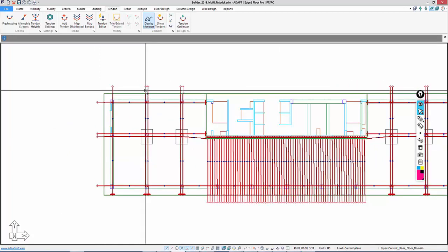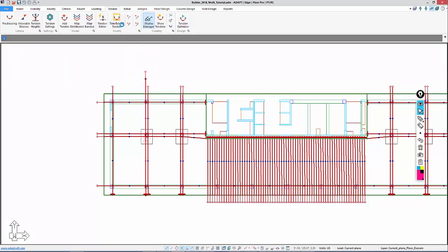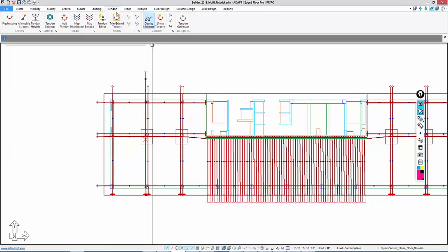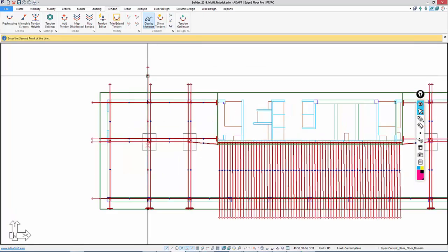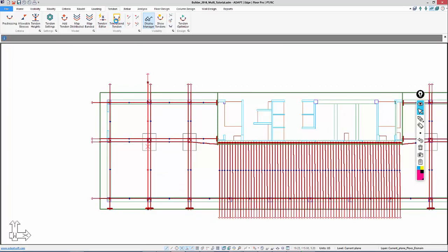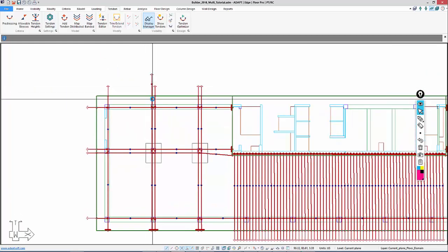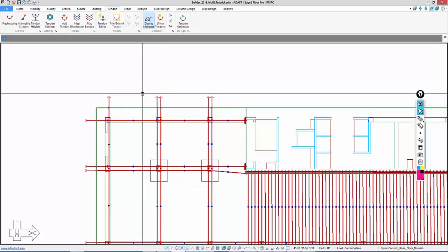If there's so much of a slab or a tendon end that's outside or inside of the slab, for example, if this is way out here and I wanted to trim it, it's not going to trim unless our tolerance exceeds that distance. So I can always change the tolerance here. If I change this to 7 feet, and then I try to trim that, that still may be more than 7. If I drag this down some and try to trim extend, again, that still may be more than 7. So just make sure that you set the tolerance to a proper distance. I don't know how far this is out, but I can just go back and set that back manually if needed. So we'll go do that like so.